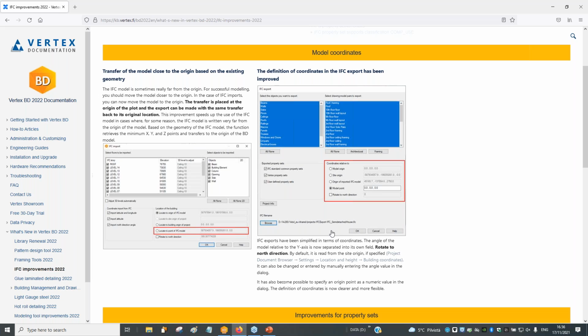Now it's possible to place origin and save the coordinates from existing point, and after that when you are exporting that, you can also fix to the same coordinate area, so that it's going to the right place. So now it's better. And you can also change the model points or north direction and rotate with that if you want.